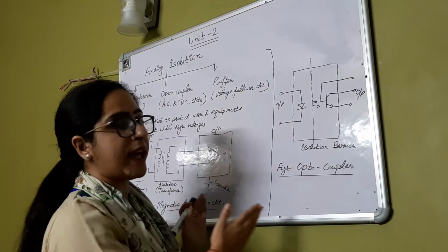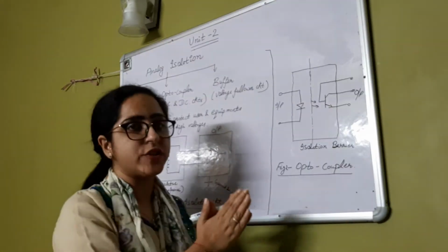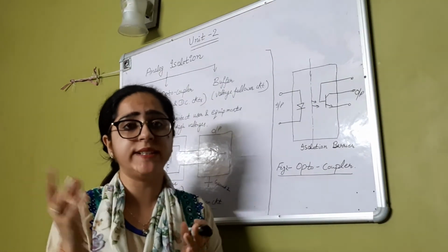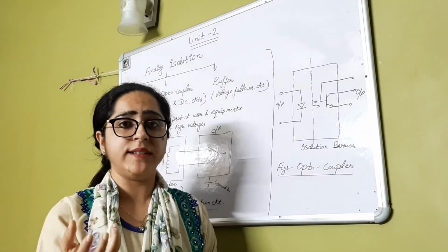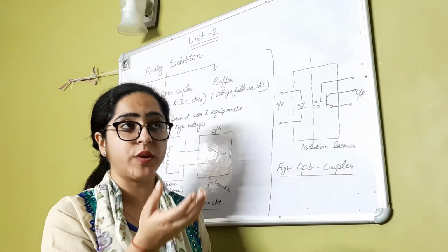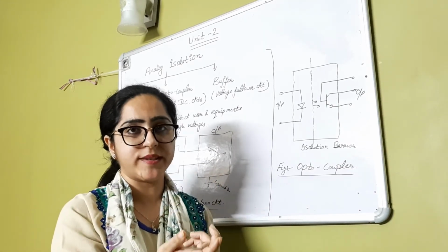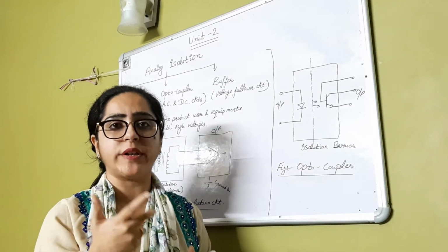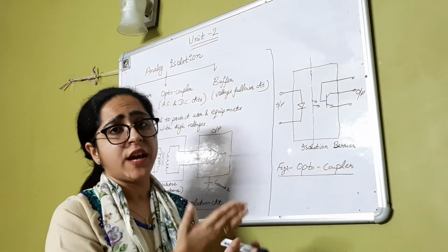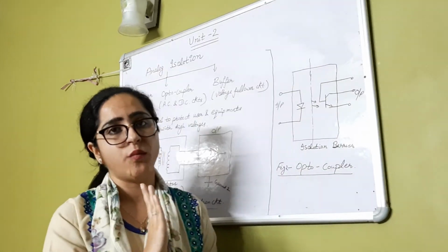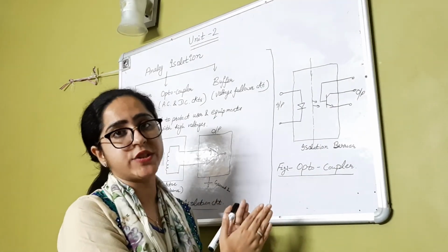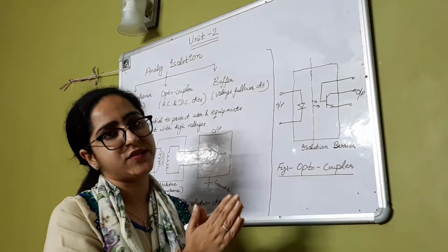So this is all about analog isolation. Analog isolation is done just to isolate the DAQ system so it can work in a harsh environment, to control and monitor any process in the harsh environment, and also to protect the operator working in the console room with the computers from any hazardous voltages, spikes or transient conditions. For that purpose only, analog isolation as well as digital isolation is used.